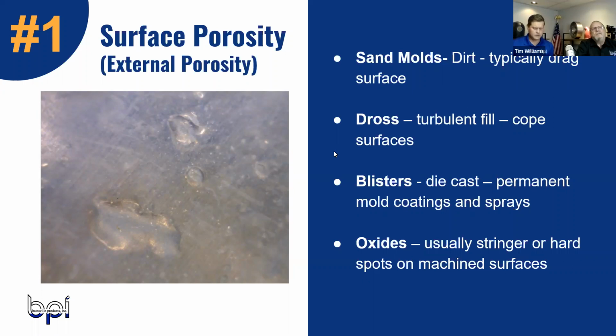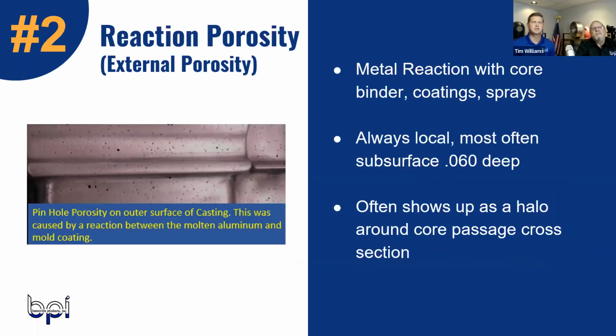Okay. So the next one we'll talk about here would be the reaction porosity. And I think we actually had kind of a quick conversation before we got on. We have a part here, and Monty, I don't know if you want to talk a little bit more about that part. What we're trying to do is not necessarily on the casting side, but on the sand core side. Yes, we have a problem with sand sticking into the casting and not coming out, even in heat treat. So we're trying to use a coating on the core and see if that helps at all.